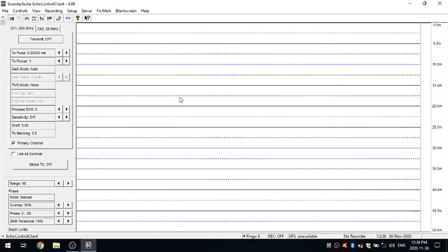Hello again, everyone. In today's video, we're going to talk about the different file recording options that you have with your Knudsen Echo Sounder and Echo Control Science software application. So if we go up to our recording option here, you'll see there were three different options you have: start line, end line, and configure.